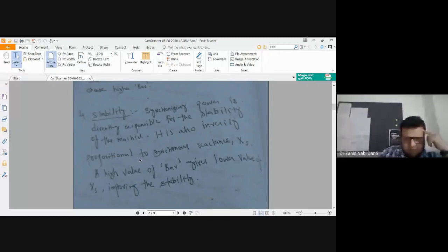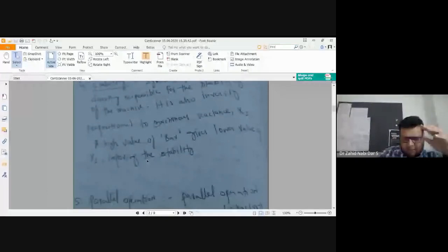So this power is the synchronizing power, which is generated by the alternator, and it is given by the terminal voltage and the excitation voltage. That is E into V divided by X into sine delta. And delta is the load torque angle between E and V. Have you heard now, Viramani? You have studied this, right? Yes, sir. Your power would be equal to this, you have studied it before.